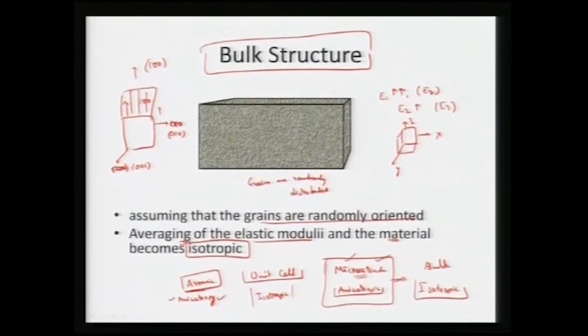If we want to get an additive property, we might want to align the grains along this side by controlling the solidification or by applying a certain epitaxial film on which we can start growing the material along that particular direction. Now what we can get is a net magnetic domain along this 100 direction, and that can be controlled. So, we can enhance the material properties by controlling something at that scale, and that will yield a better engineering property via application of understanding the material at nano length scale.